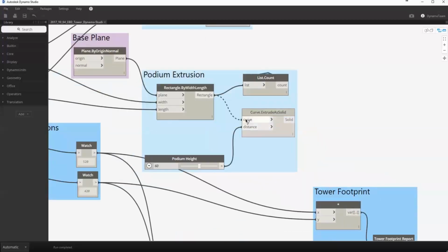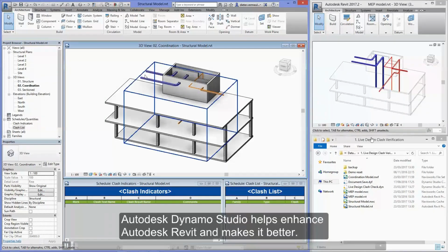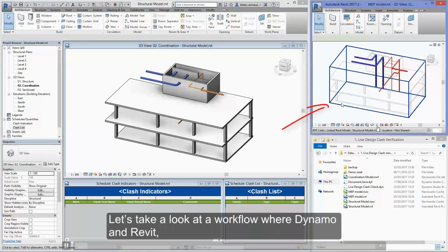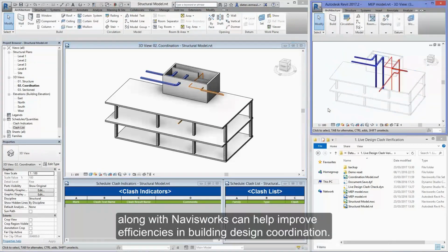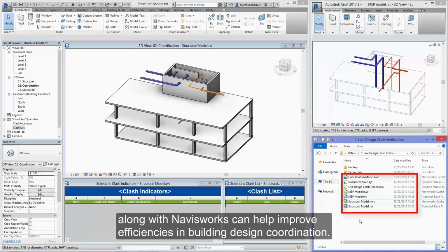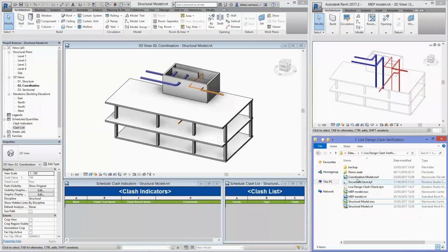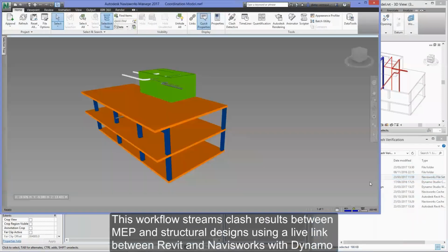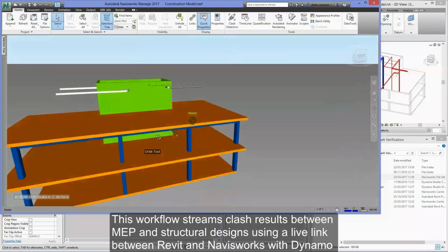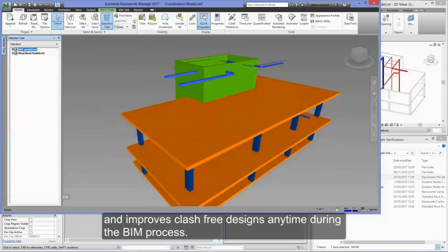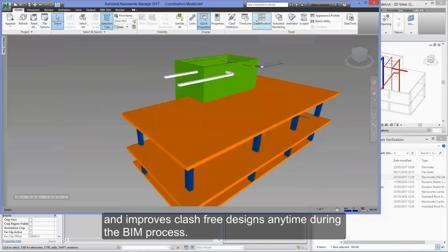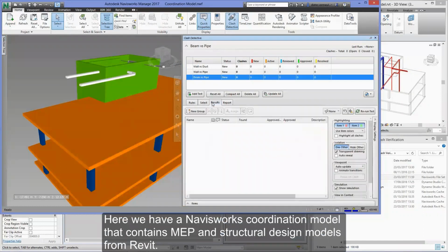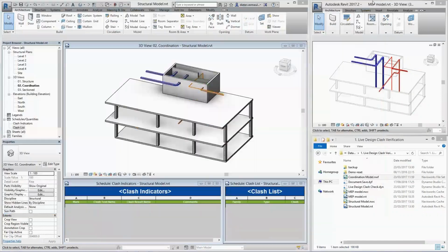And as I mentioned, there are fairly practical examples of this as well. So looking at creating clash detection within Revit itself, not going into Navisworks. So what this has done, it's taking your design coordination information from Navisworks, and it's going to place an object wherever it finds a clash within Revit as well. So this is our clash detection that we might have run previously in Navisworks. So we're going to take all of those clashes and we're going to push them into Revit, and we're going to use Dynamo to place an identifier object of those clashes within Revit as well.